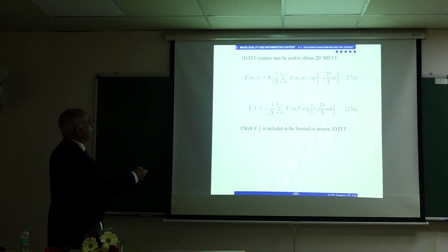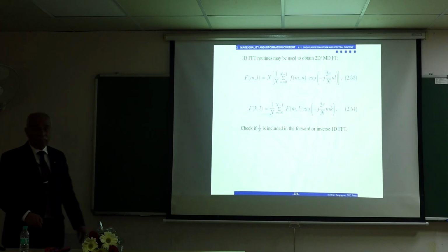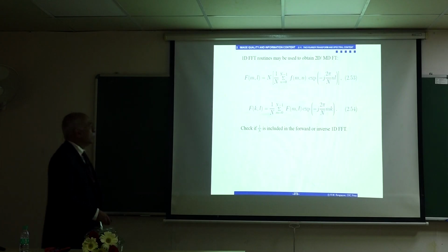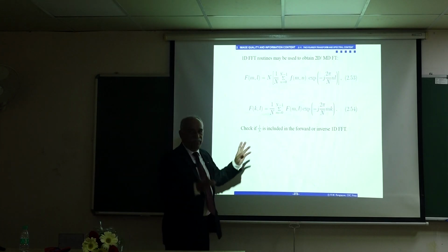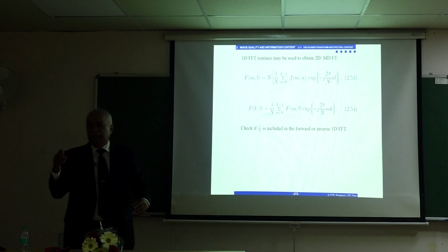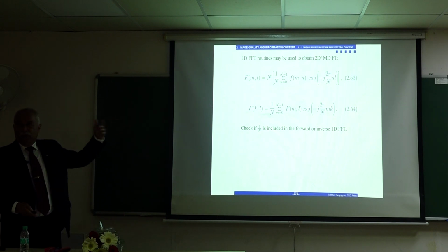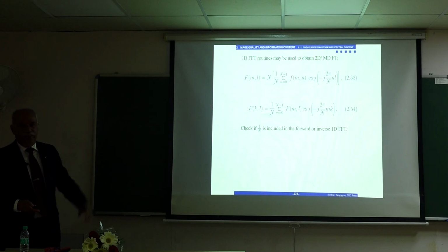Take the result of this F(m,l), and apply another DFT on it, using m as the index. You can do this first, and then that, it doesn't matter. So 1 over N is a factor that you need to check if your FFT algorithm has inside or outside. But if you're scaling using log and so on, it doesn't matter.